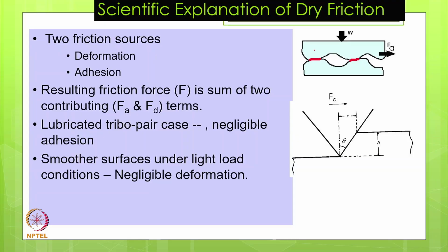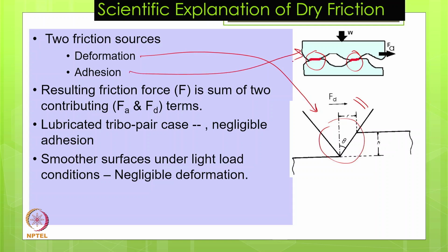In the same way we have covered wear, now we can think about friction. Again, the same thing. Adhesion: when two surfaces come into contact, there is a cold junction and it needs to be ruptured. So that's adhesion. Now, if a conical asperity is harder, it will not break, and we need to plow the soft surface. That comes under abrasion in this case. However, instead of abrasion, we say deformation, because it is going to deform the surface. And adhesion is the same mechanism we followed for the adhesive wear.